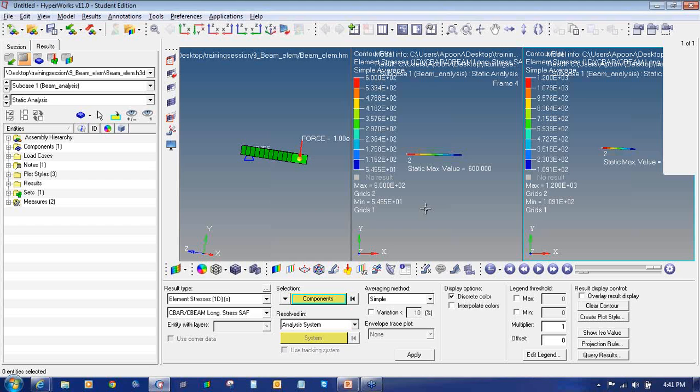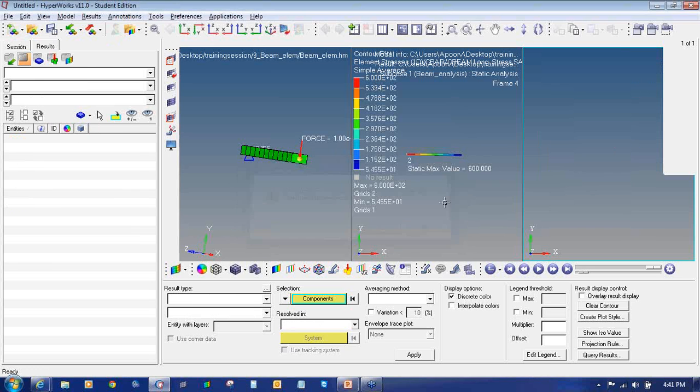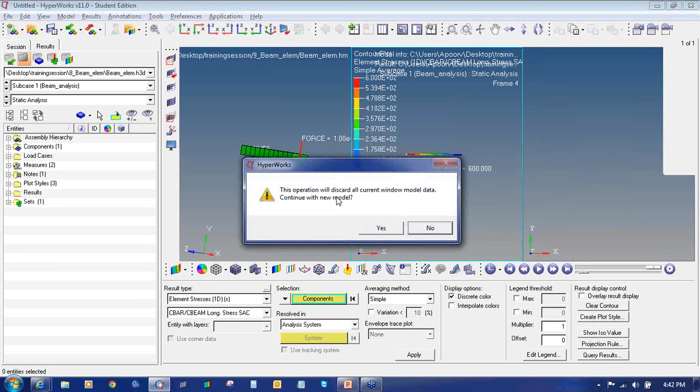If you are using a cross section in which the dimensions are different, if you are using the same dimension cross section, that is square or circle, then the orientation will not play a major role. But if you are using a cross section as a rectangular, I section or L section, then the orientation plays a very important role. So in this way, we have ended with this.